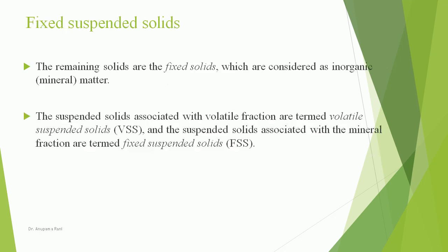Next is fixed suspended solids, FSS. The remaining solids are the fixed solids, which are considered as inorganic mineral matter. The suspended solids associated with the volatile fraction are termed volatile suspended solids, VSS, and the suspended solids associated with the mineral fraction are termed fixed suspended solids, FSS.